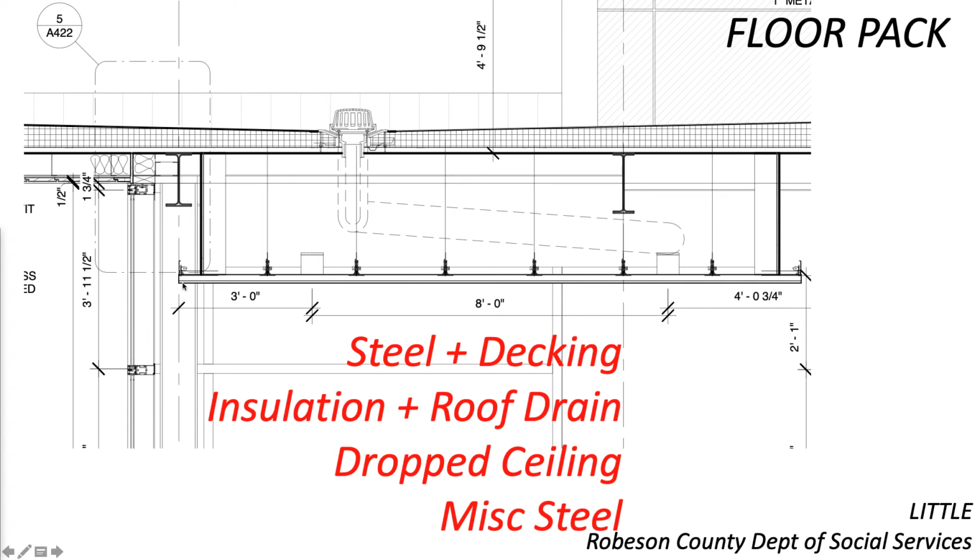Also important here, and what I like, is that there is a conscious attempt to think about the relationship of this dropped ceiling to the glass wall. In this case, the dropped ceiling is held back from the wall, giving us this nice relief, but also allowing more light to come in through this side. So this could be a formal idea or a practical idea with lighting. You will see the insulation line from the windows, which are inherently insulated, all the way up here, that they've created some additional protective insulation to keep a good thermal barrier from this outer space to this inner space.